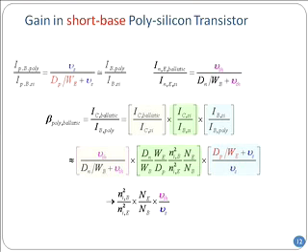If my V thermal is much smaller than the diffusion one, this is in the black, the first term, in that case what will happen? Exactly the same way, I have to drop V thermal, and the magenta V thermal in the numerator is the only one that's going to survive. As a result, you can see now the gain is given by the ratio of the thermal velocity divided by the surface recombination velocity.